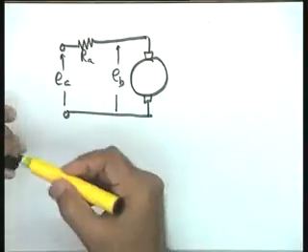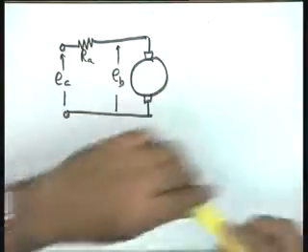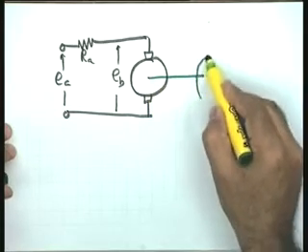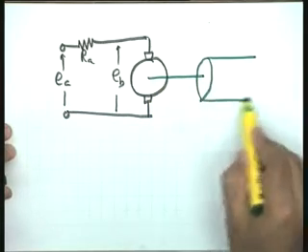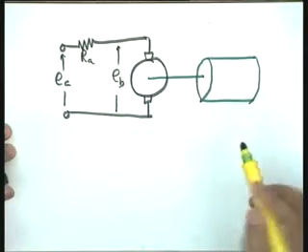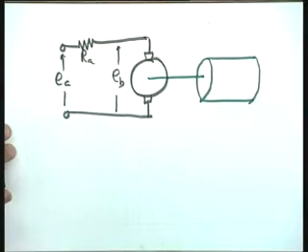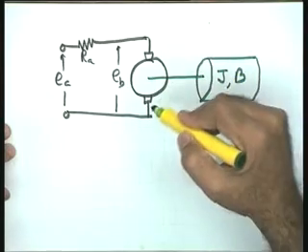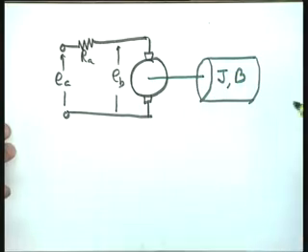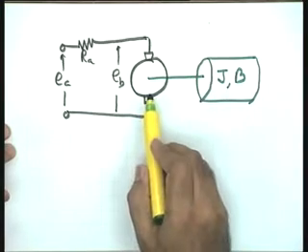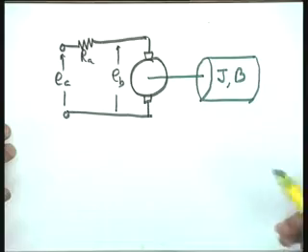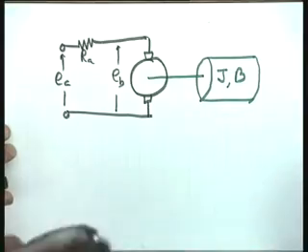Okay. Now, let me write directly, assuming that on this motor there is a load through the gear train. However, now I am equipped to write this load directly over here, and I can drop the letters equivalent also, if you understand. I will say that J and B are the parameters of the load on the motor shaft. Equivalent subscript I am avoiding, because now it is clear to me, if I am taking a load on the motor shaft, naturally if the load is through a gear train, the reflection on the motor shaft will have to be taken.